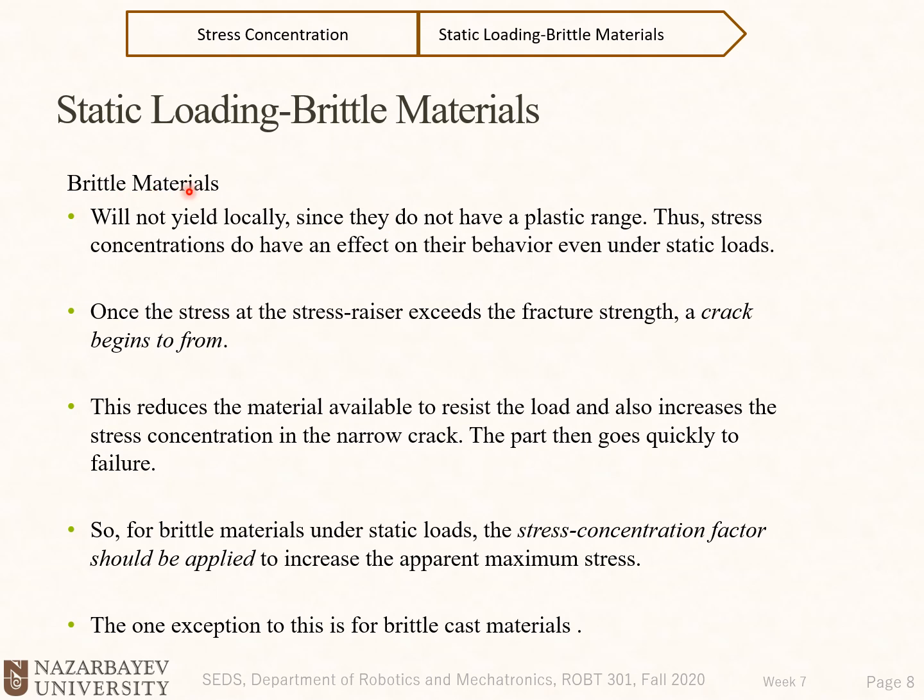What about brittle materials? They will not yield locally. Why? Because brittle materials don't have room to have plastic deformation. Since they do not have a plastic range, stress concentrations do have an effect on their behavior even under static loads. Be careful again, this discussion is about static loads for both brittle and ductile materials.